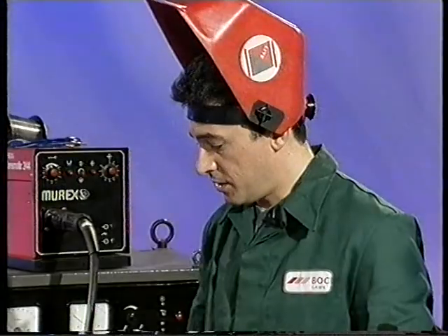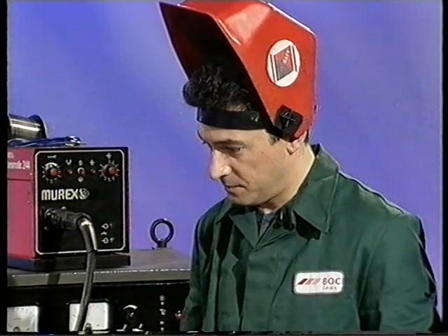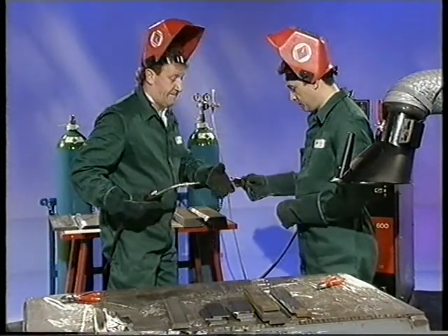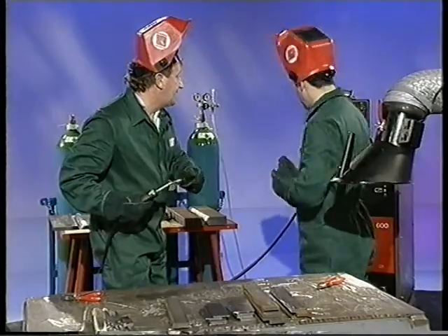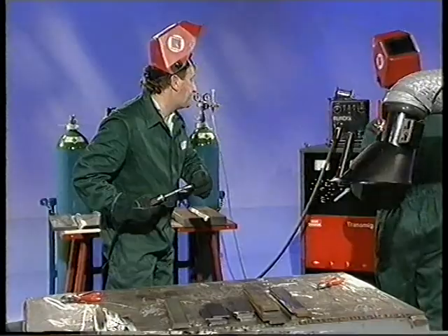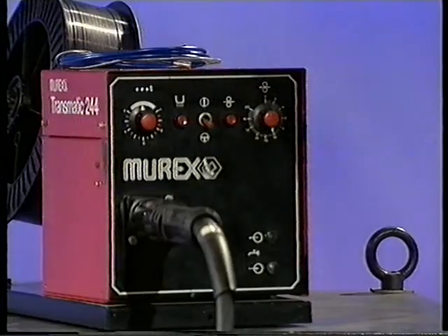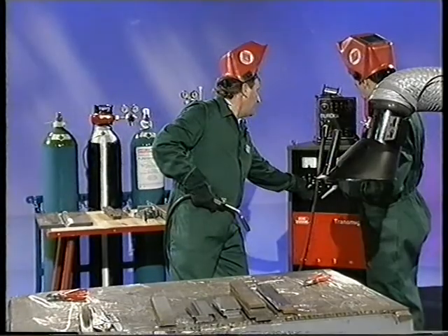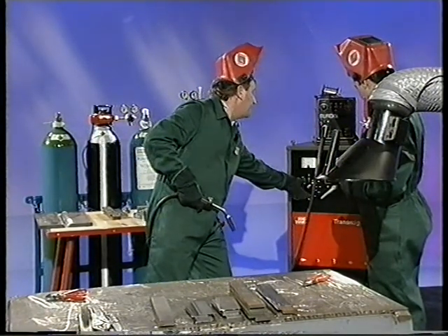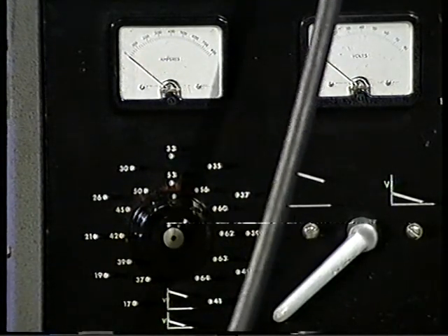Right. Just in case, I brought the other nozzle. Okay, you've got a spray nozzle there. We'll put that on because we are going to go up to spray transfer after globular dip. Thank you. And if you would please put the wire feed speed up to around 10 meters a minute. Right. And we'll increase the voltage, but not too much. The figures on the outside of the machine here are indicating the open circuit voltage, and generally welding voltage is 6-8 volts below that.